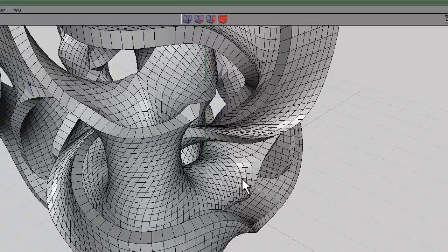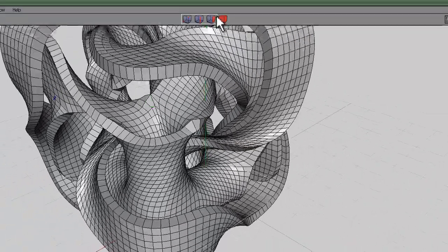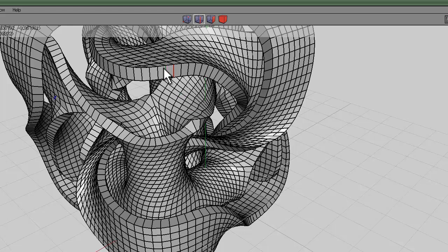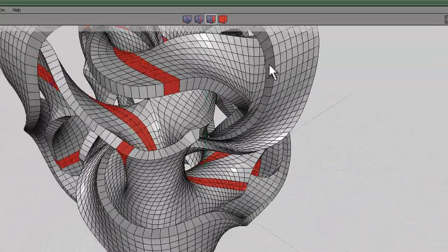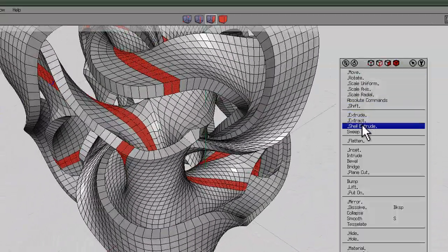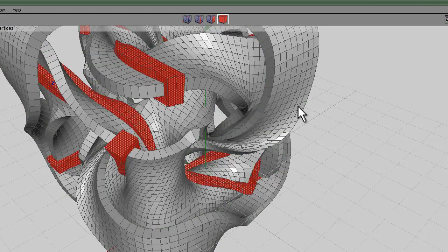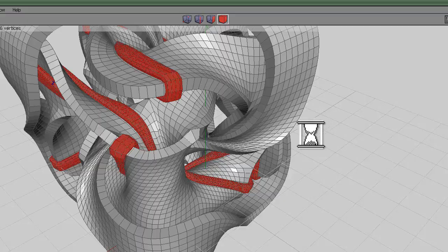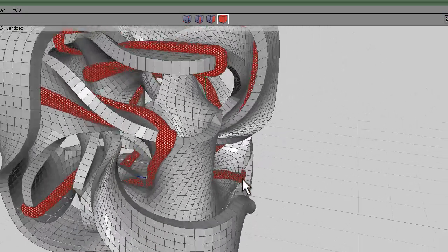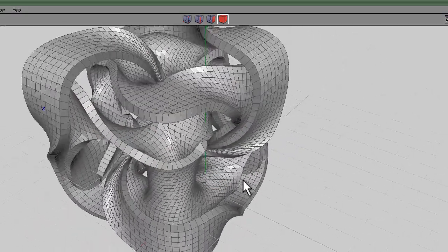I mean, obviously you could do other things with this shape, like you could wrap lines around it, so you could select an edge like that, use identical and then loop, and then you could get lines wrapped around it and shell extrude normal and do this kind of thing, and then smooth that down to create some interesting loops around the object. I'm not going to do that, I was just demonstrating.